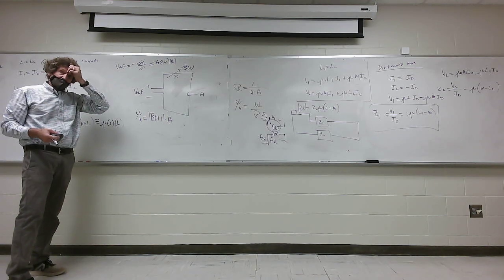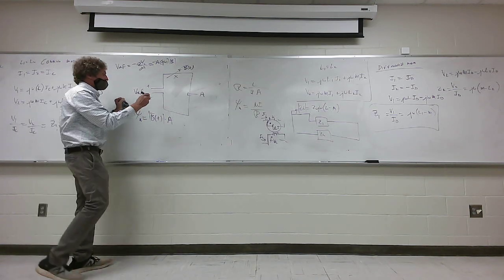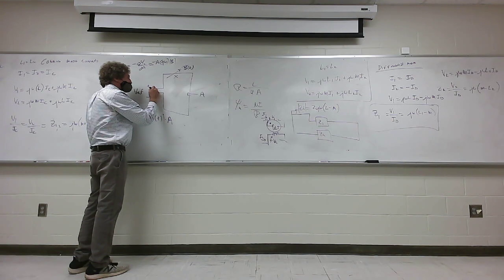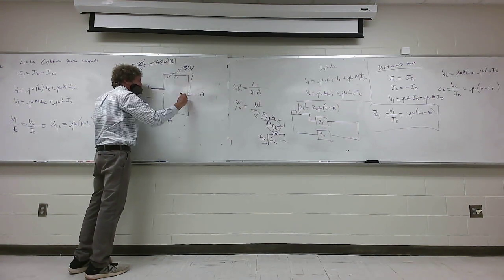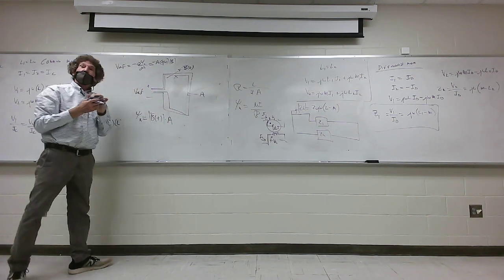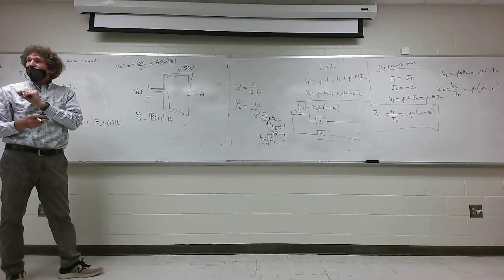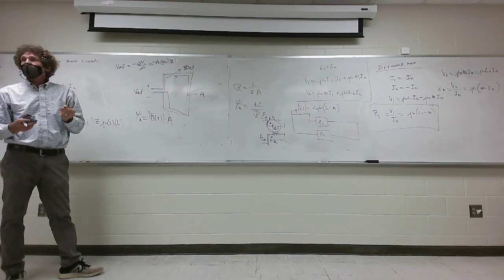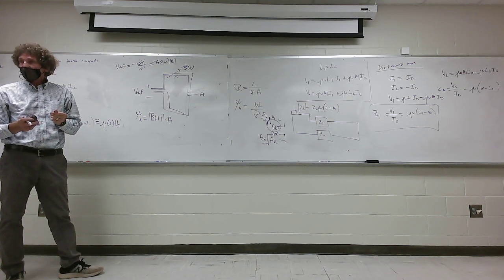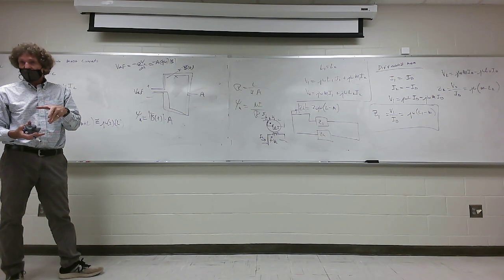Y'all follow me? Now what if you have a simple extension cord where 2 of these go in parallel? Y'all see that voltage is across both of those, driving current in the same direction in both of those? So that's a common mode current, and it's caused by a ground loop that's actually having a magnetic field inducing it. You with me?